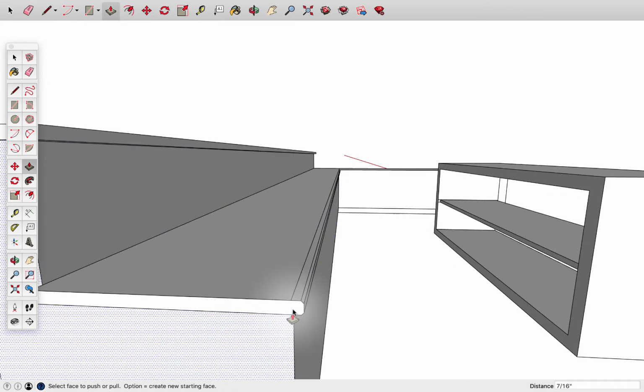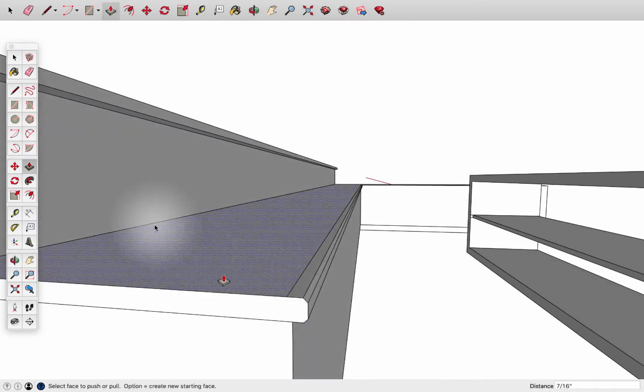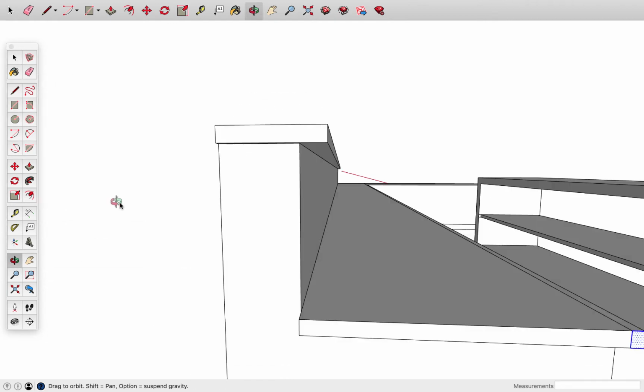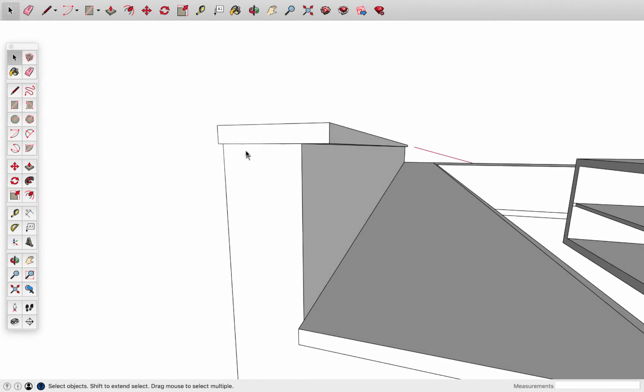Now, what if I wanted to copy this profile up to this countertop? Well, what I'd need to do is get to a point where I can copy the profile. And you need to draw in a line somewhere along the line. Somewhere along the line. That was an unintended pun. So that you can copy that profile. I'm just going to double click on it, select it, and here is where you can use the System Control-C and then go up to this upper profile and use Control-V.